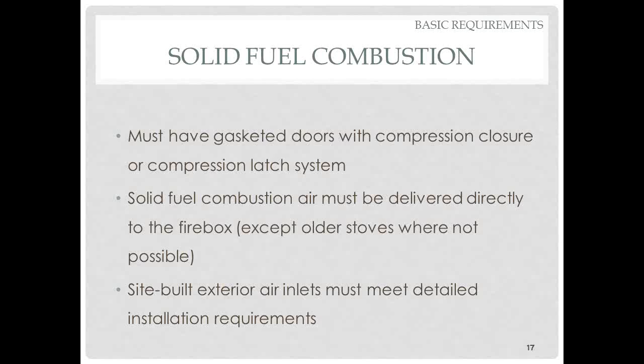You can either do that with a manufacturer-approved kit, or in the case of a site-built fireplace, you might be doing a site-built exterior air supply. And if you're doing that, you need to look at the code for the specific requirements for site-built combustion air to solid fuel devices.